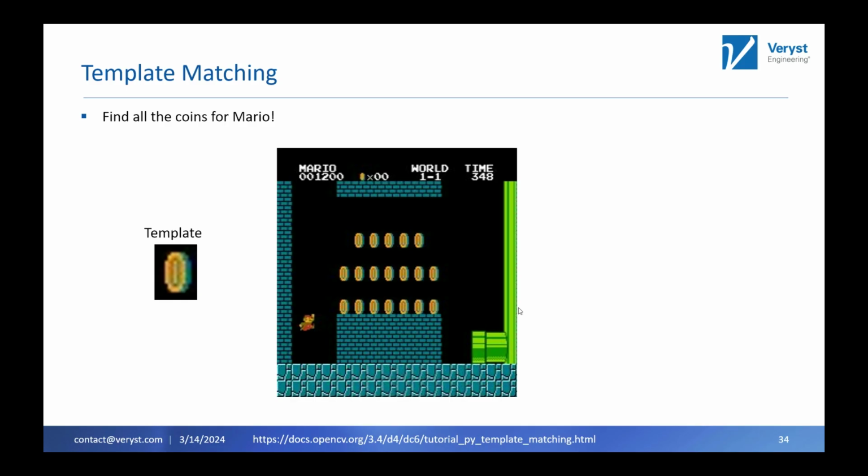Before we go any further, I do want to talk about a little bit of the detail in the computer vision algorithm and how we actually determine the location of the crack tip. We use a process called template matching. In the computer vision world, there is software designed for this, and OpenCV particularly is the package that we use. That's the phrase you want to look up to learn more about this procedure. But I've got a toy example here that illustrates the process that we're going to use to keep track of the crack tip during the test.